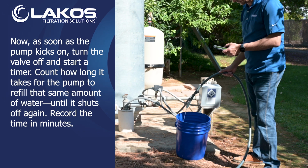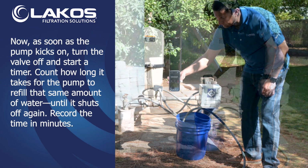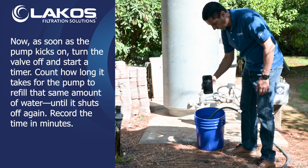Now, as soon as the pump kicks on, turn the valve off and start a timer. Count how long it takes for the pump to refill that same amount of water until it shuts off again. Record the time in minutes.